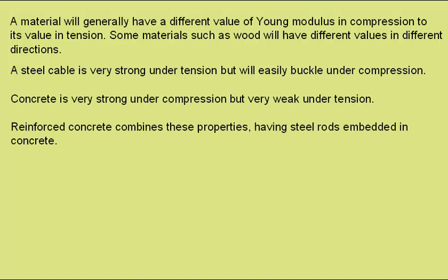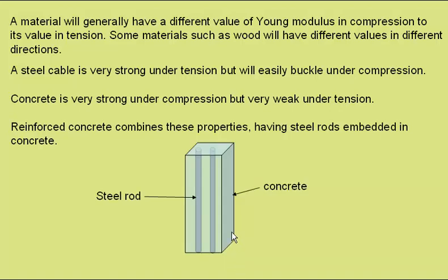Reinforced concrete combines these properties. It has steel rods embedded in concrete. So here we have a block of concrete, inside which are a couple of steel rods. The steel rods will give strength in tension. The concrete has strength in compression.